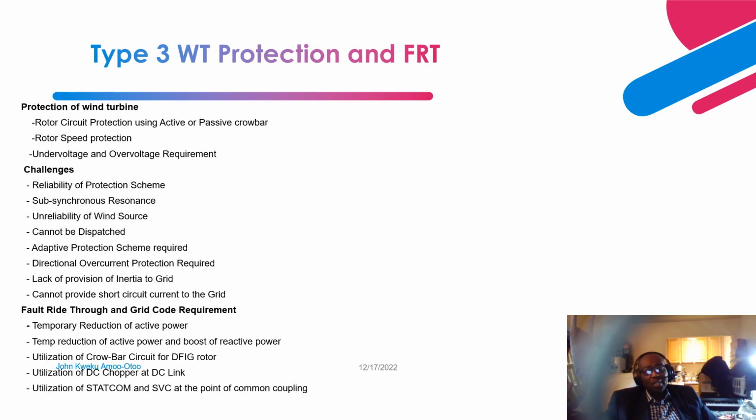And when there's a fault, definitely short circuit current flows for the relay elements to detect that fault. Inverter-based resources, wind farms and solar PV, lack that capability. They don't have the inherent capability of providing short-circuit support to the grid. As such, there is a decrease in short-circuit capability of the existing grid as these synchronous generators are being decommissioned, due to the goal to achieve net zero and carbon reduction.